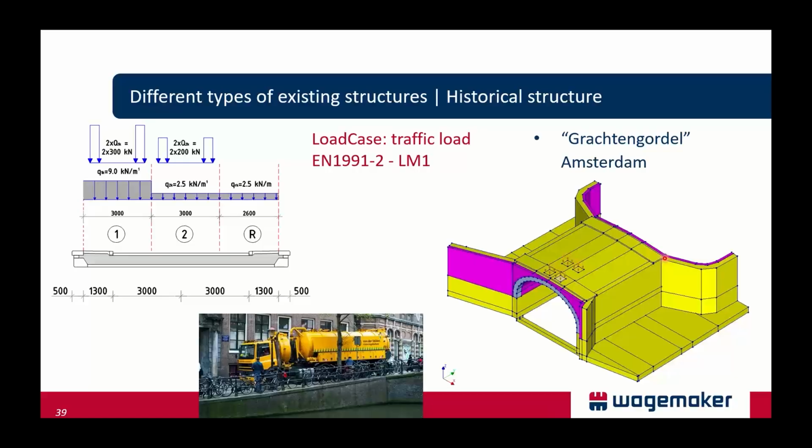On the right-hand side, we see a load model 1 tandem system in the middle of the bridge deck, and this was modeled using quadrilateral loading, which doesn't affect the finite element mesh.